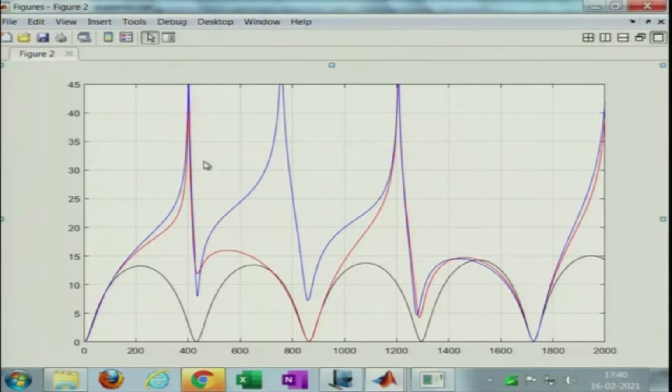But now when we have extensions at both inlet and outlet, 0.5 L and 0.25 L, the performance kind of enhances at higher frequencies, I mean beyond this. Although we would still see a trough here, the trough is lifted significantly. But another interesting thing is that even by choosing L by 4 we are not able to cancel the second trough, which we were able to cancel for a simple expansion chamber with extension.